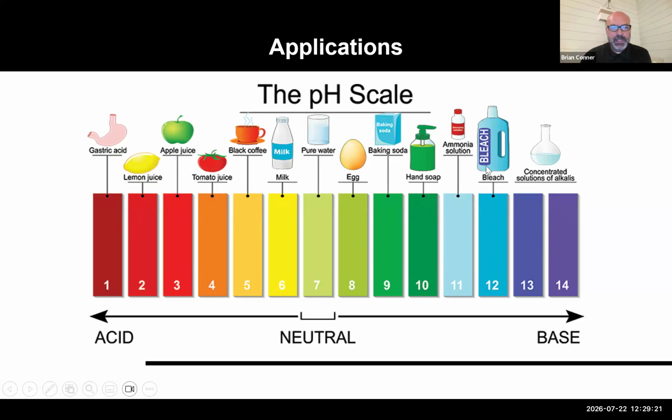So here you see the pH scale. Lots of these things go down the drains every single day. It's not until you get to some of these really aggressive effluents that the code details that you need special waste for that. You know, folks wouldn't think that apple juice or lemon juice or tomato juice can be very aggressive, but they can. And then this 3 pH range is also where you find soda fountains. So most sodas are in the 3 pH, and it's very aggressive to metallic piping systems.